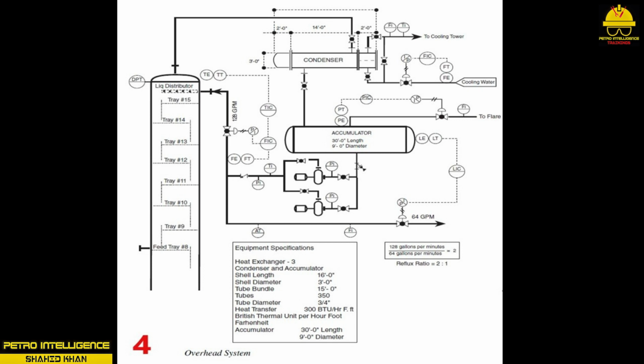Frequently, the reflux flow controller is cascaded to a master temperature controller at the top of the column. The reflux rate and cooling water flow rate to the condenser can significantly impact product purity and temperature. Reflux ratios will vary between different applications and are carefully calculated before the first pump or pipe is installed. It is important for a technician to understand the complex relationship the reflux ratio provides to a successful operation.